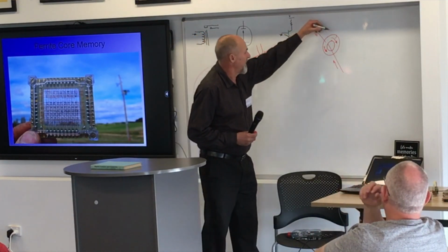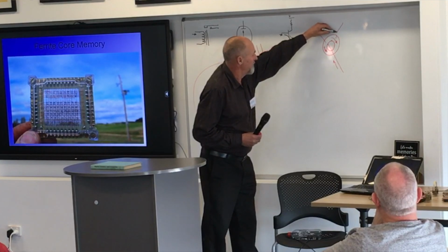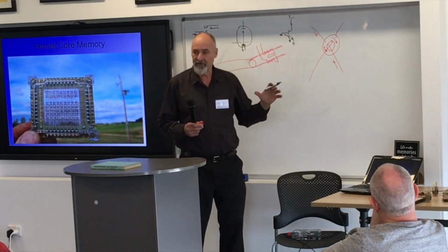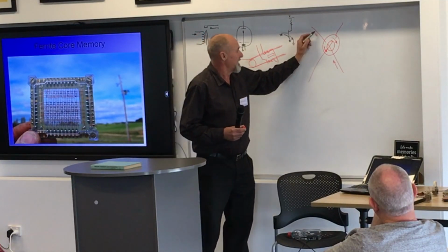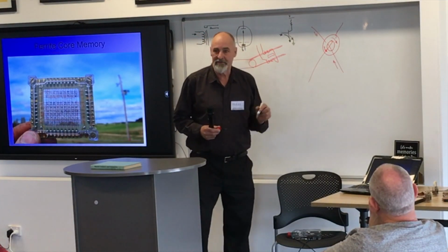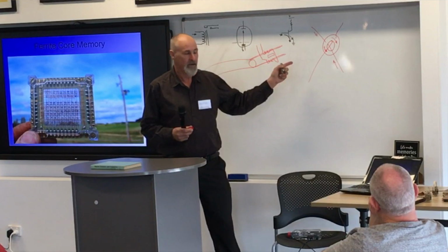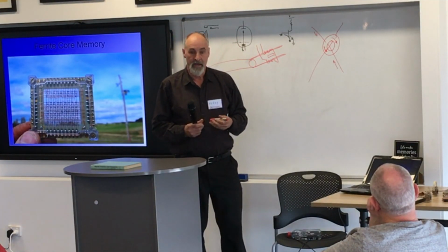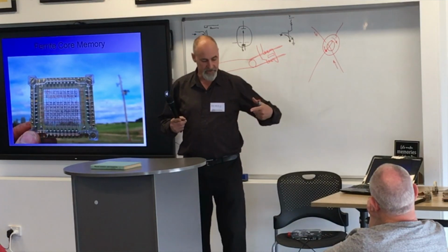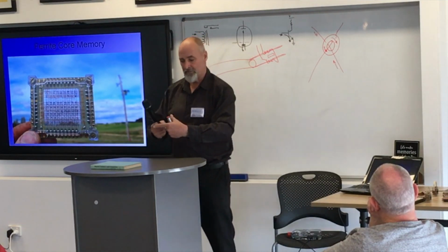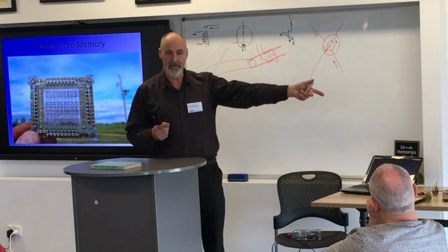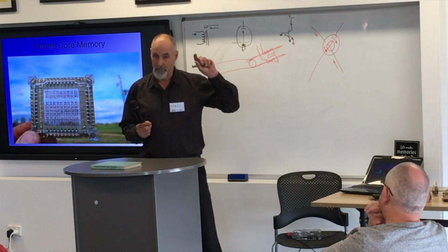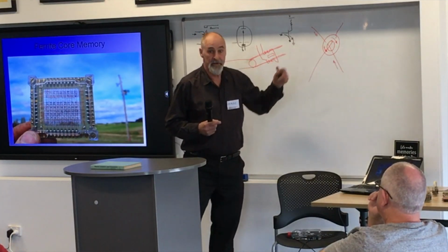So the trick is to have 2 wires, because we've got to address a whole bunch of memory, and we make neither of these enough to magnetise the core, but the sum of the 2 enough to magnetise it. That means that we can energise the X row and the Y row and select one of 16,000 ferrite beads on a panel like that one there, and magnetise it one way or the other.